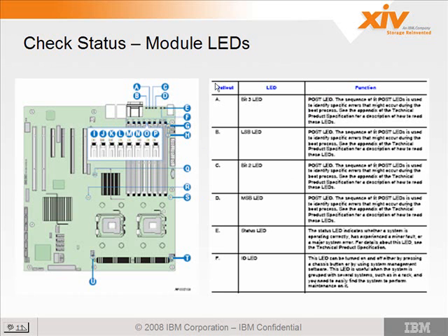So here's a picture of the motherboard in the actual modules, and the LEDs that we're concerned with are A through F, the ones that you can see through the back of the enclosure. And there's a website you could go to for this Intel motherboard, and it basically tells you what each position means, like this is the bit 3 LED, contains a post code, least significant bit LED, another post code.